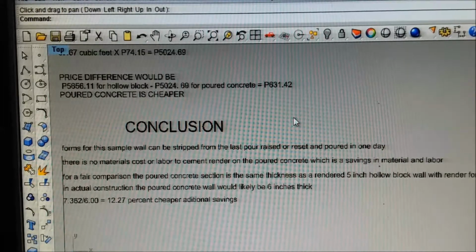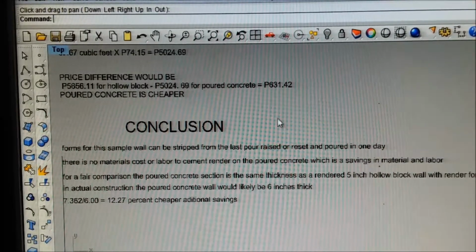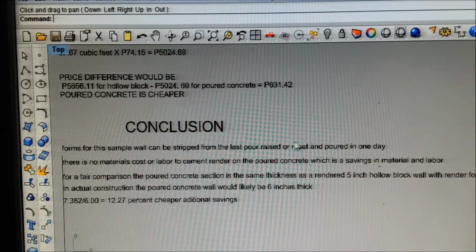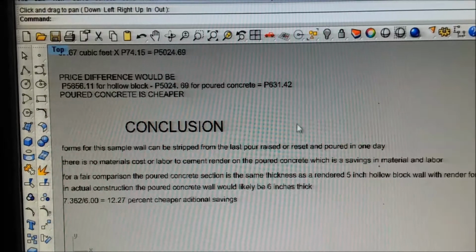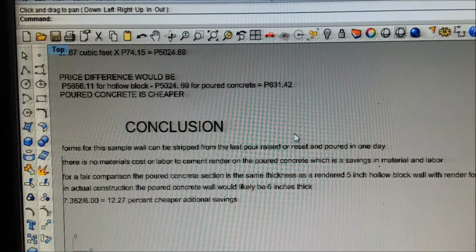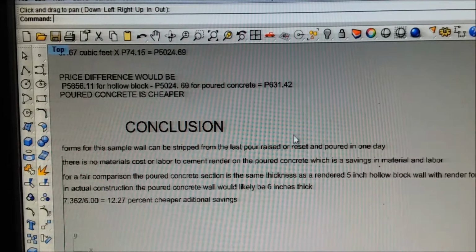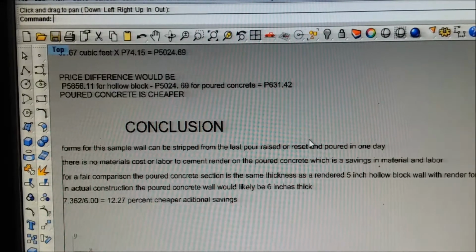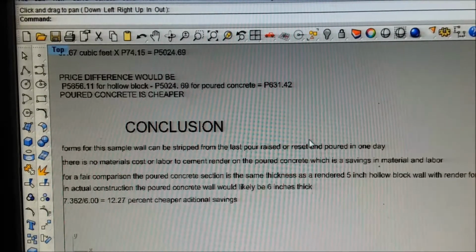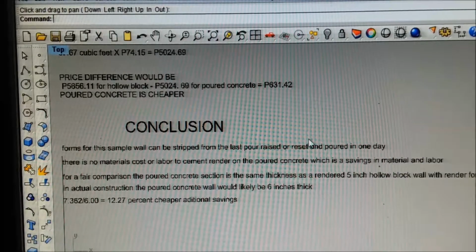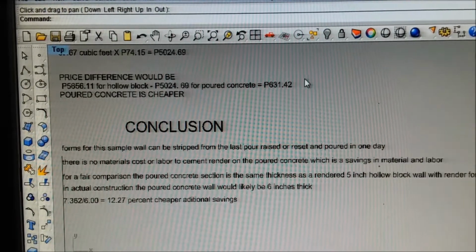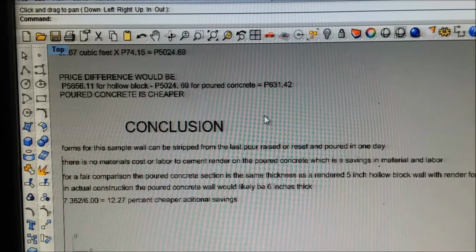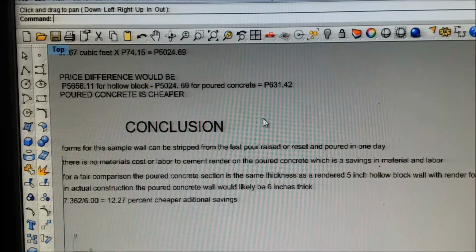cut at a 45, and then a 2-foot form on the side of that piece that's set on top of the 8-foot sheet, and that made us our 14-inch wide beam on the top, with no leak between the two pieces. I mean, nothing ran out because it was forms on forms. And it gave us a surface on the top to strike it off. And we had a lot of places we could get leverage up there to put tie wire and keep the rebar centered where it was supposed to be. So if I was pouring tall walls, I'd probably use those kind of forms again.